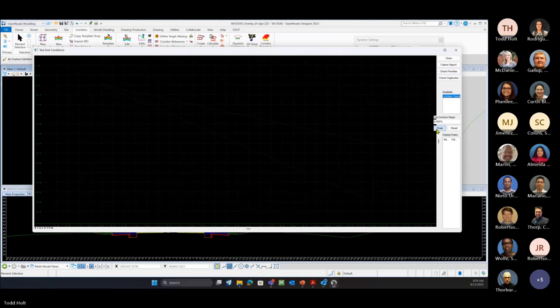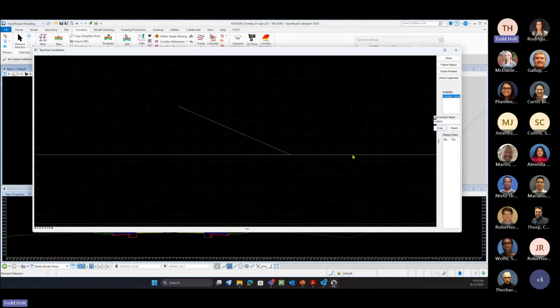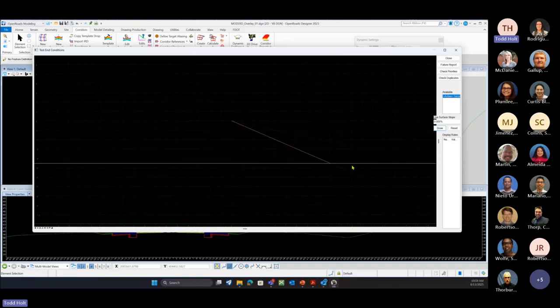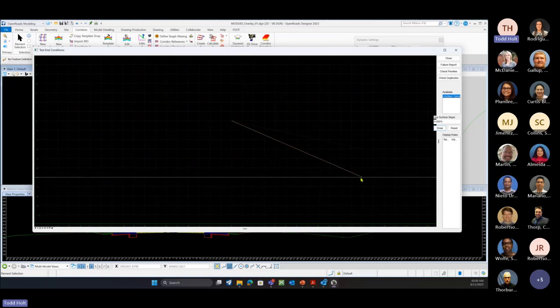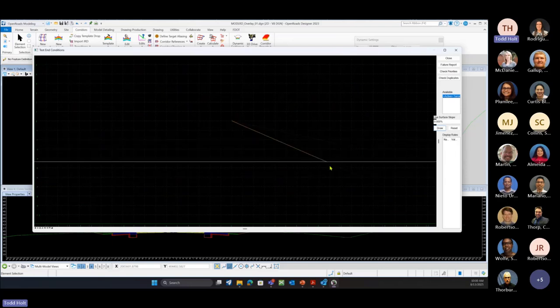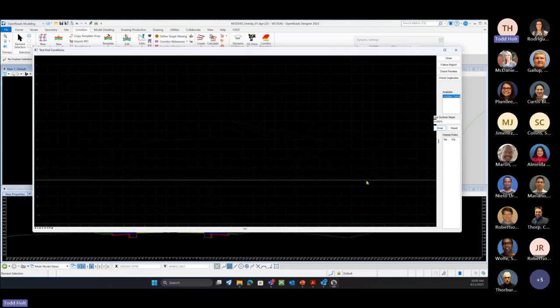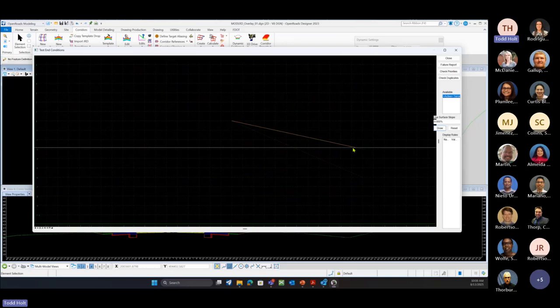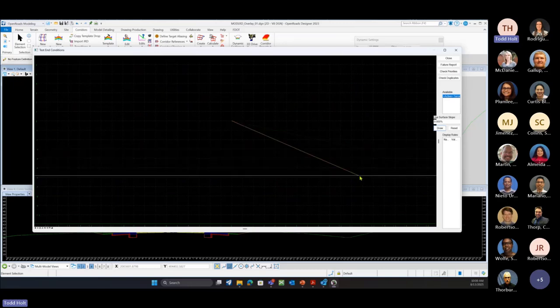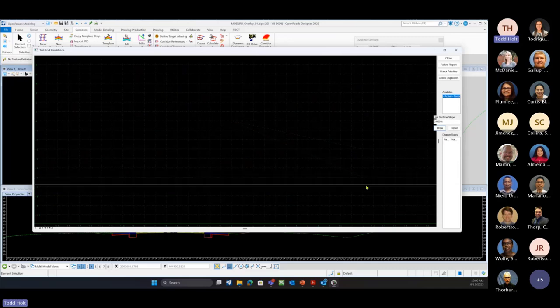And if we test, it's going to draw that 1 to 4 slope until it gets to the extents, and then it's going to move on to our second solution. So it's treeing off and having multiple solutions, but then it's only going to go on if we had a 1 to 6 or another slope, or a 1 to 8 slope past that. So on one of these, or that last solution, is where you want to pick the end condition is infinite. So it's going to search for this. If it can't find it, it's going to move on to the next solution. If it couldn't find that, it's going to move on to the next, or this last solution is going to be our end condition is infinite.